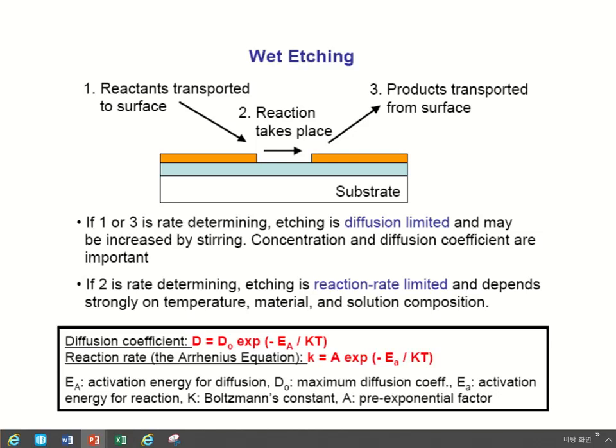So when you do wet etching, you shake your device during the etching, because the shaking guarantees a uniform etching rate over the whole wafer.